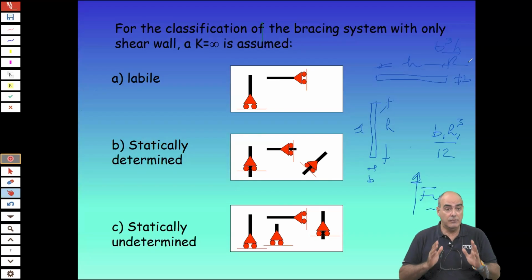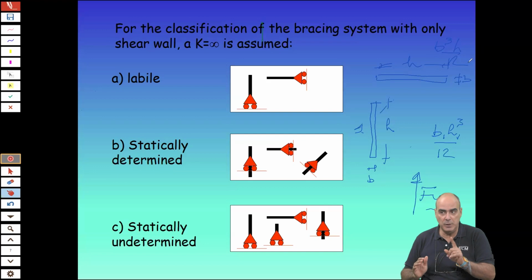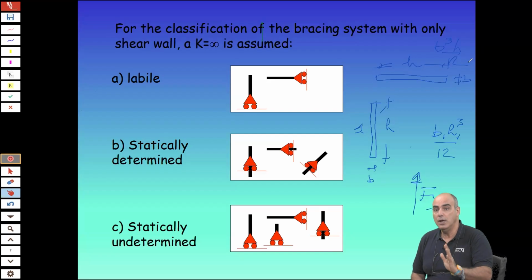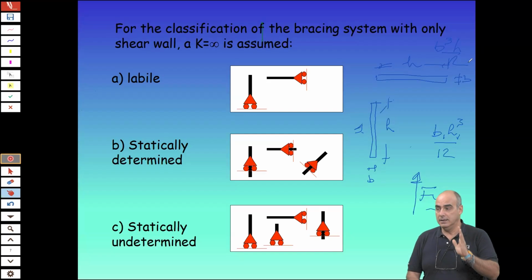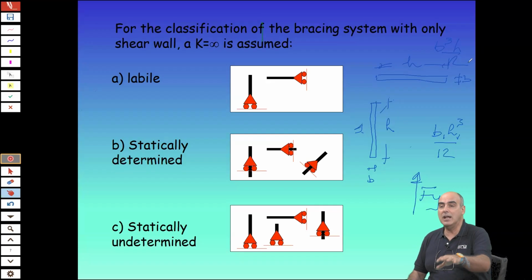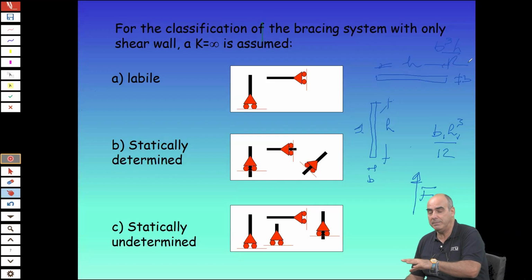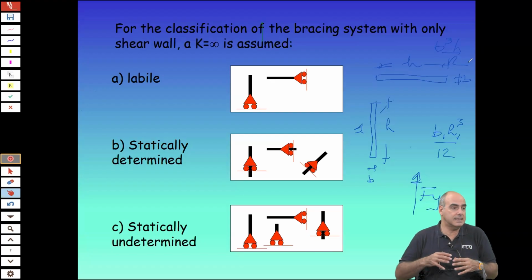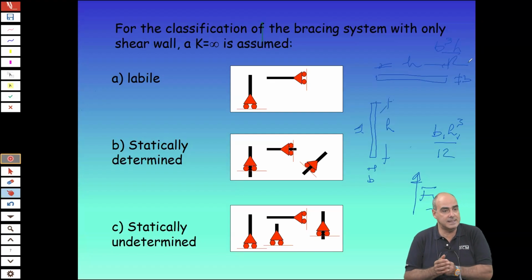And we say for the effects of the forces, we will see that for the effects of the torsion, it's not like that. For the effects of the force, we only consider the walls that are parallel to the force. It's not that the others do not participate, but simply, since their contribution to the stiffness in that direction is 2 orders of magnitude lower, we can neglect it.